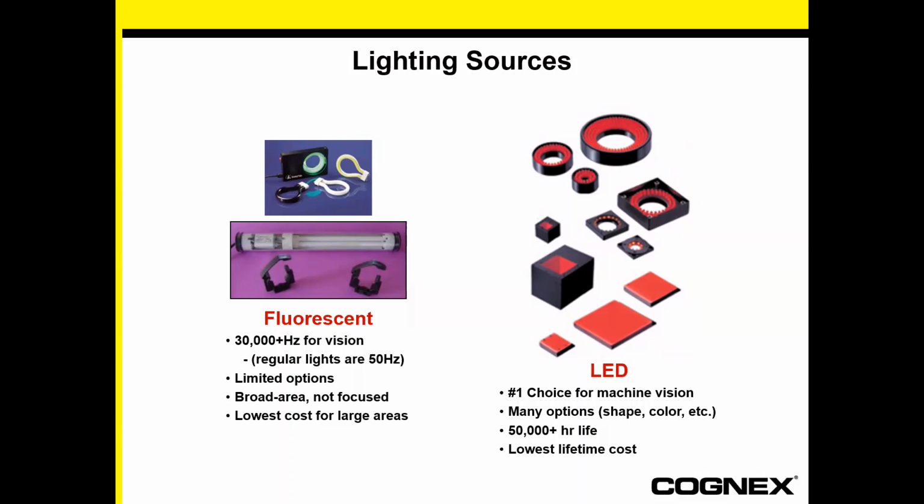All the way through to, you might have on a production line, you need lights on there and you need them flashing to get extra brightness. You don't want to interfere with the operator, so we've used infrared light, which is in a spectrum that humans can't see, but the part will be highlighted. The camera can still see at that wavelength. So there's lots of different options.